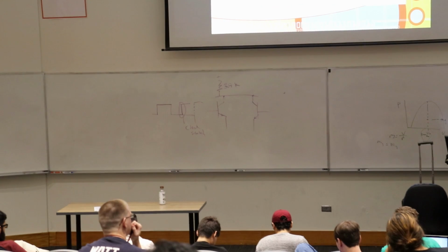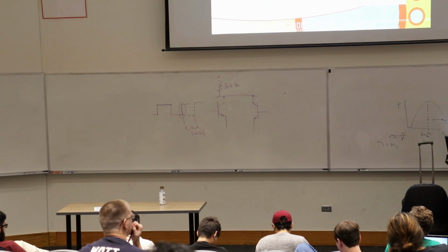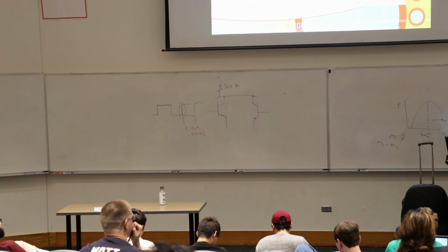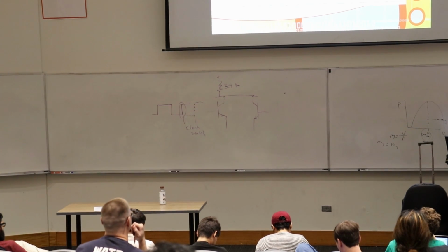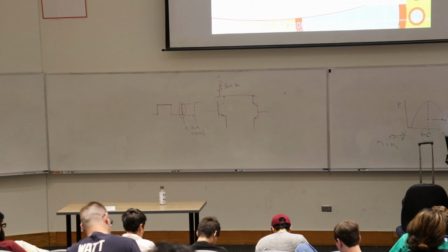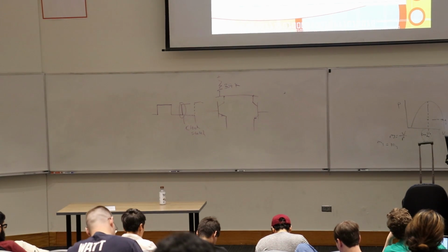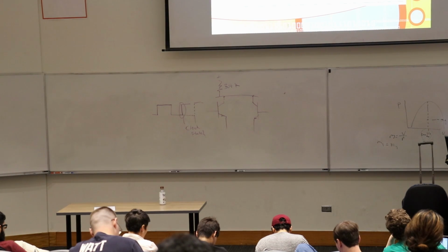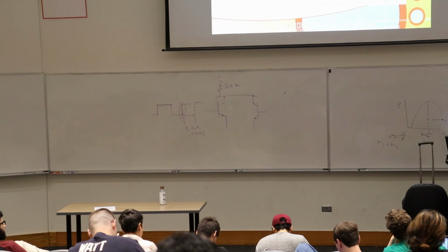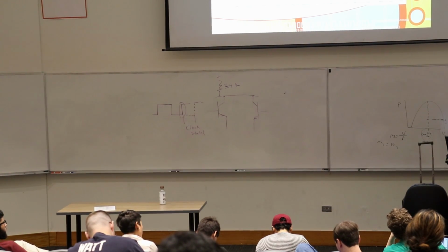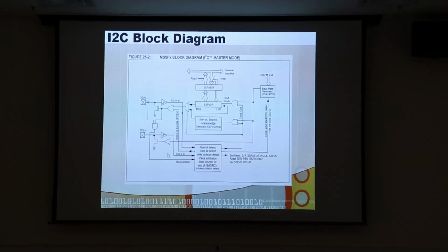But the backplane in your desktop and laptop, the so-called PCI bus, it is a parallel bus. So go figure. Anyway, but that bus is pretty tightly controlled. It's not a wire. It's actually a printed circuit board with very careful attention to end termination, and so you don't have to worry about skew so much on that. But you do have to worry about data traveling down a parallel cable at different rates, and when you really try and push it fast, that gets you into trouble, and you can have unpredictable results, and that's why they've gone to serial interfaces. Okay, the memory's still parallel though.